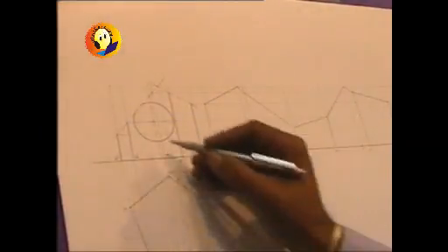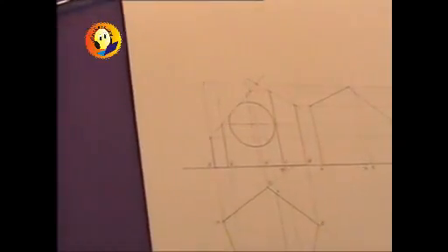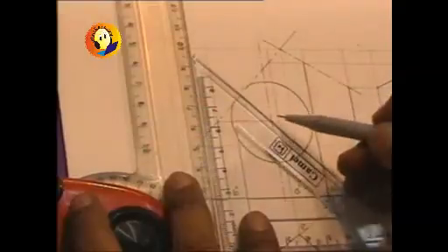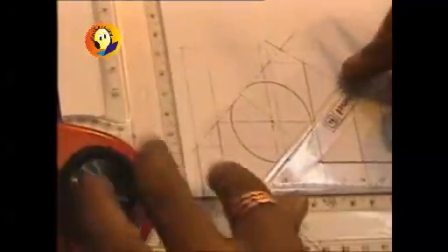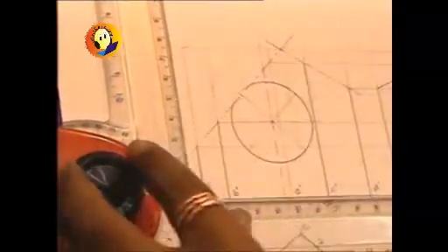Generator E is yet to be darkened because the circle comes into picture, and to mark that circle, now there is a lot of construction which is to be made, and for that matter we will proceed with some more generators to be drawn on the front view. We will divide that circle into 8 parts. Generally it should be 12, but in this case it will be very crowded, so I am just dividing it into 8 parts. 4 are already there, so another 4 parts, so it is 8 parts.